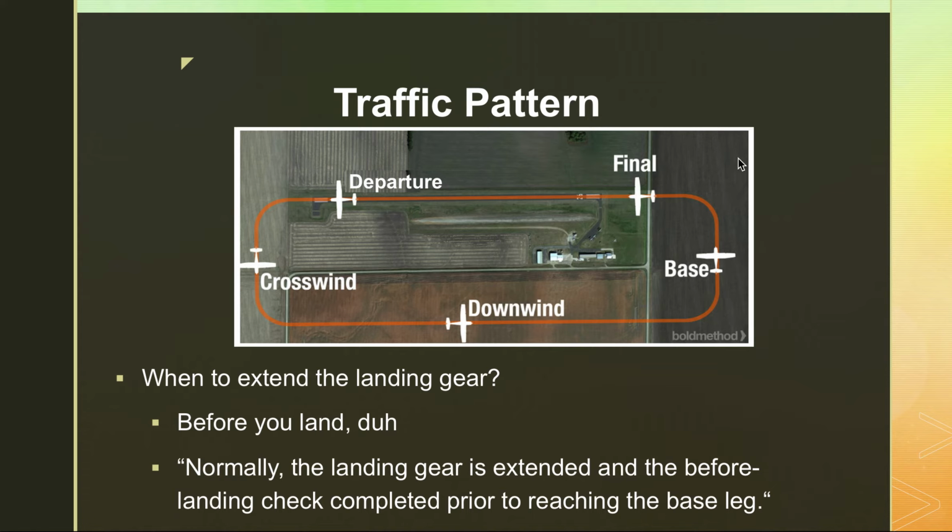It's kind of dangerous. If I'm doing a straight-in landing, you don't have a downwind or a base. So what I do then is, depending how fast the airplane is, 3 mile final is downwind, 2 mile final is base, 1 mile final is final. That pretty much gives you the same amount of time that you had in a traffic pattern. That's pretty close to the dimensions you're flying here. If you're flying a really fast airplane, though, that doesn't give you enough time. So do 5 mile, 3 mile, 1 mile.